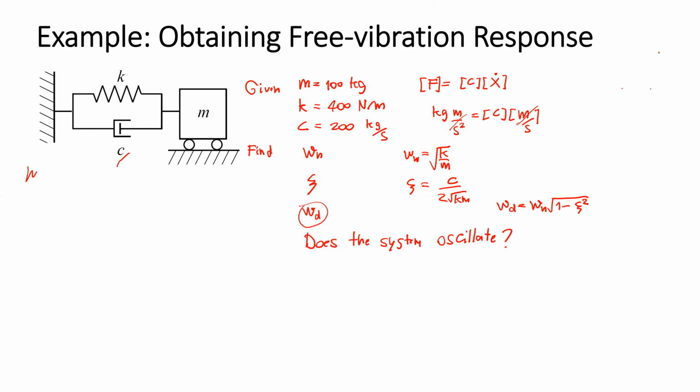So how about this question? Does the system oscillate? The system will oscillate only when the damping ratio is between 0 and 1. If the damping ratio is more than 1, the system does not oscillate.